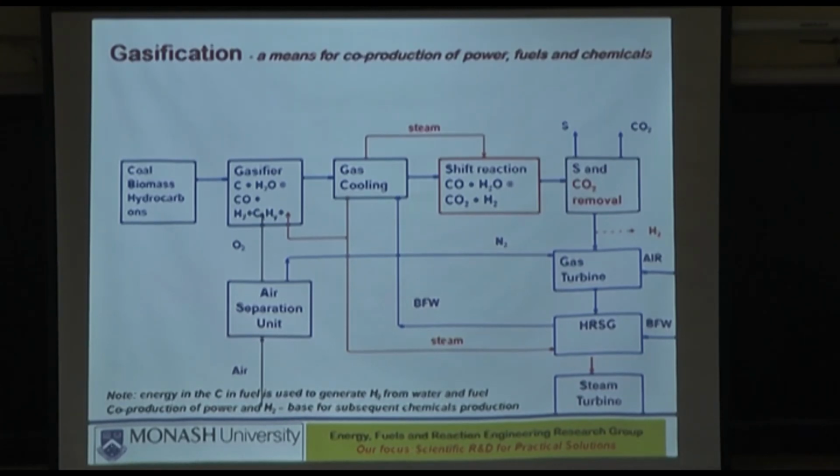Right. So, you can get a maximum amount of CO from the gasifier depending on the temperature that you are running it. Of course, if you run the gasifier at a higher temperature, means you will be producing more CO2 to generate more heat. What that will do is that will drop the CO, right?